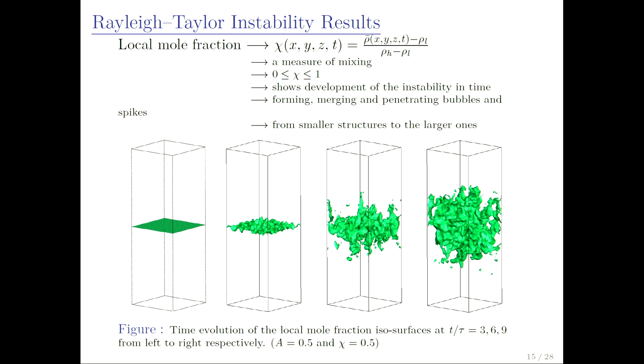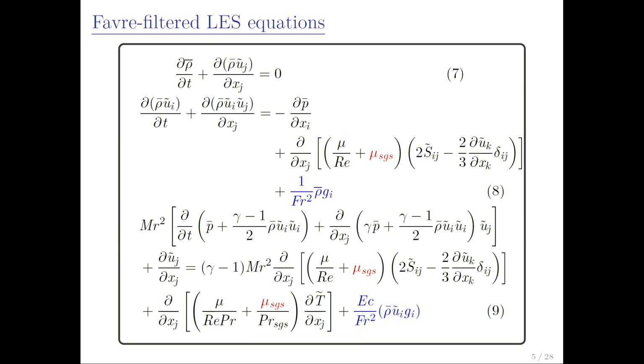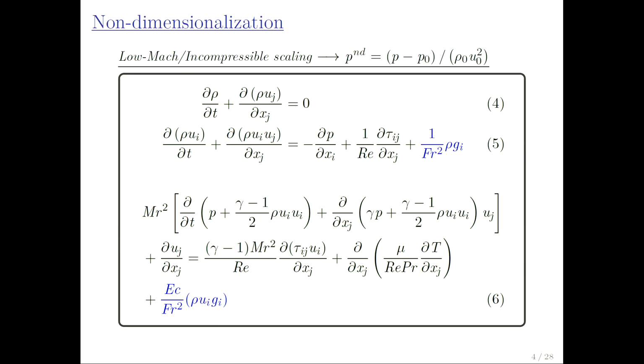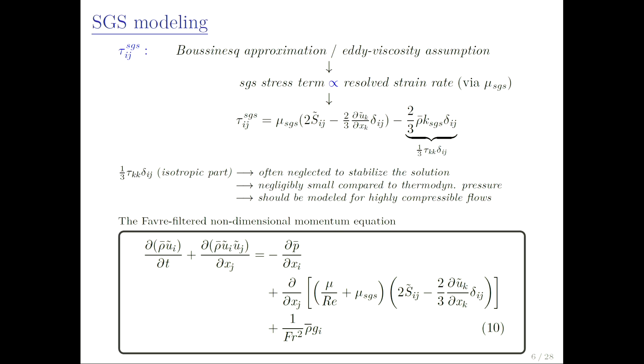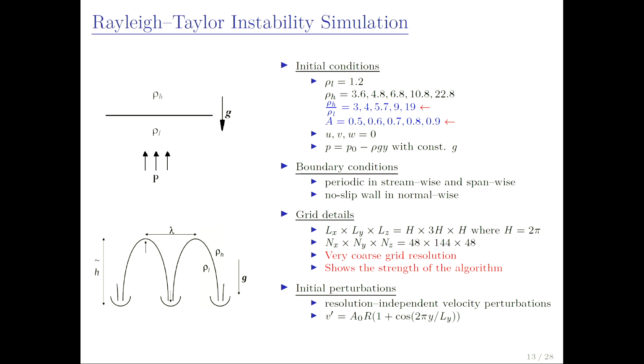So then my point is, you're not solving classical Rayleigh-Taylor instability. In Rayleigh-Taylor instability, you start with the steady state solution and then you perturb the interface. By using linear pressure, it's not steady state at all. You start with an unstable solution. It's my mistake; I tried to be fast, so I missed some details.